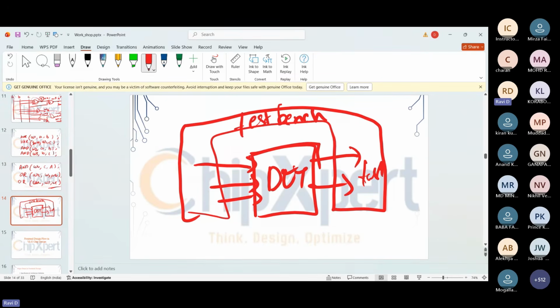It provides us the randomization concept to send the data from the test bench to the design, and to control that randomization. When we use the $random keyword, we don't have any control over it. If I use $random, it is going to generate some random value. If you want control of that, SystemVerilog provides constraints, like needing the value to be generated only from a particular range.